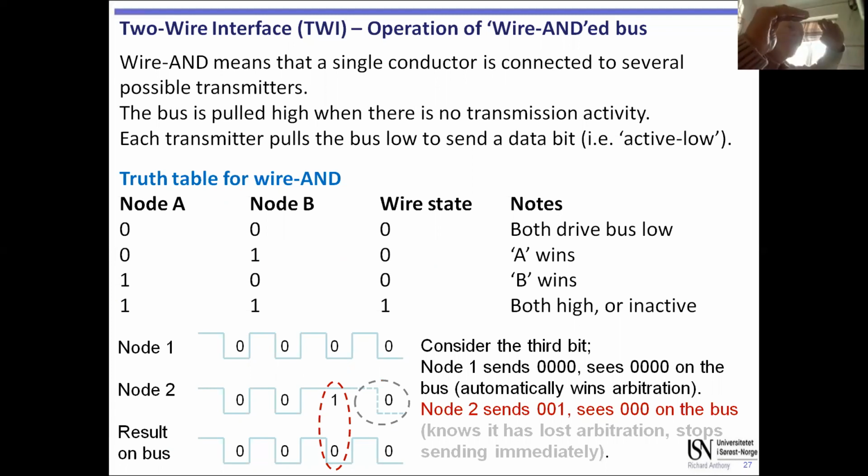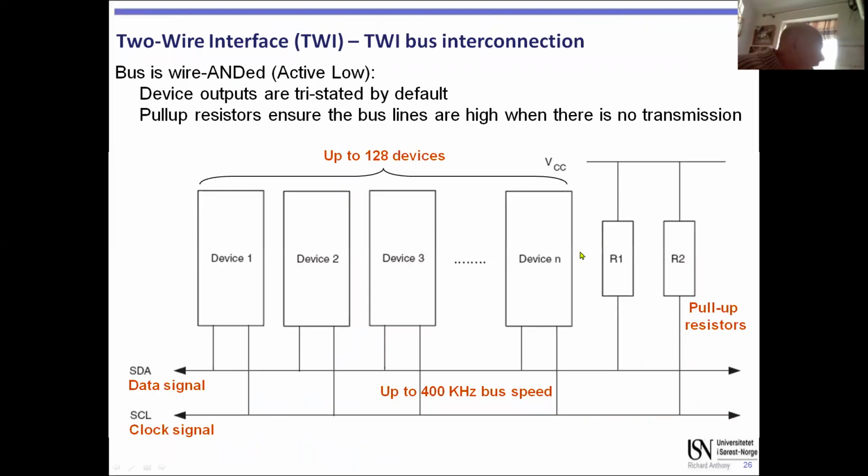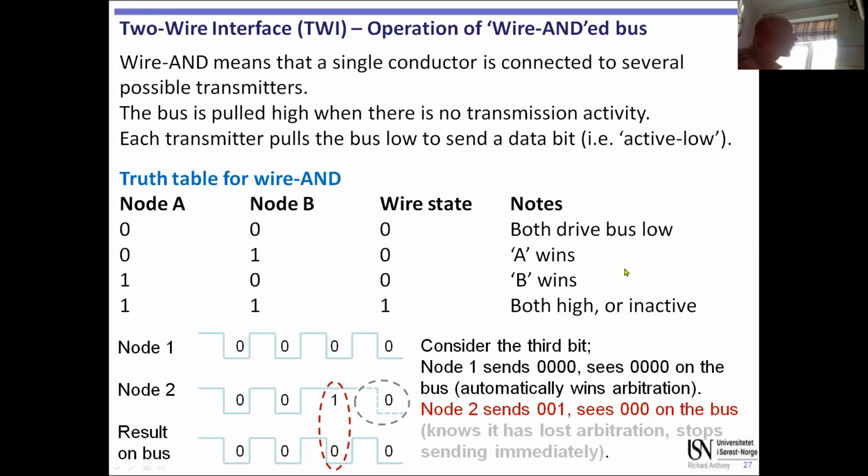So if something transmits a 0, it pulls down with strong current through a transistor. That pull-up resistor is only weak. The voltage will go down very, very easily to 0, and the resistor won't be able to overcome it. Obviously, the choice of the value of the resistor is important, and there's notes in the manual as to how you select those values, etc. You must obviously use the right value of resistor. That is important. But when you write a value such as a 0, you're pulling the value low. That's going to override a 1 where it's just floating high. So the 0 always wins.